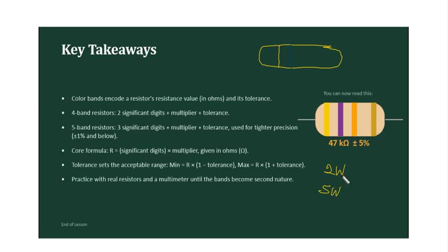The only thing that will make you know which one is 2 watts and which one is 5 watts is that the 2 watts is going to be smaller in size, while the 5 watts is going to be bigger in size. So you can have a resistor of a particular ohm value that has different sizes, and those different sizes tell you the different power ratings that are available, based on the information that comes with the data sheet or the documentation.